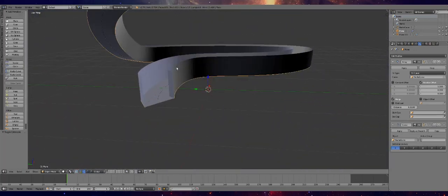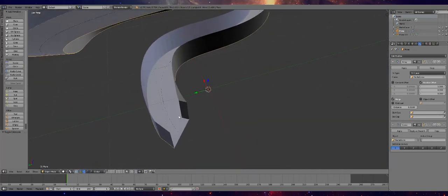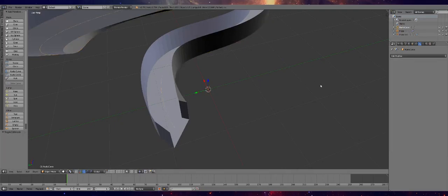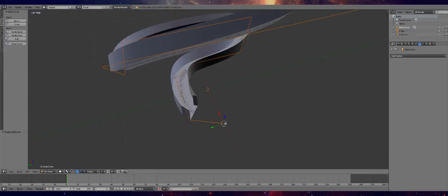So another thing we notice is, why is this wall like this, right? We don't want that wall to be there. This one specifically is caused by this NURB curve. The angle it ended is too sharp, and since it is the first part of it, you can't actually lerp between one rotation and the other, so it just creates one that's messed up.